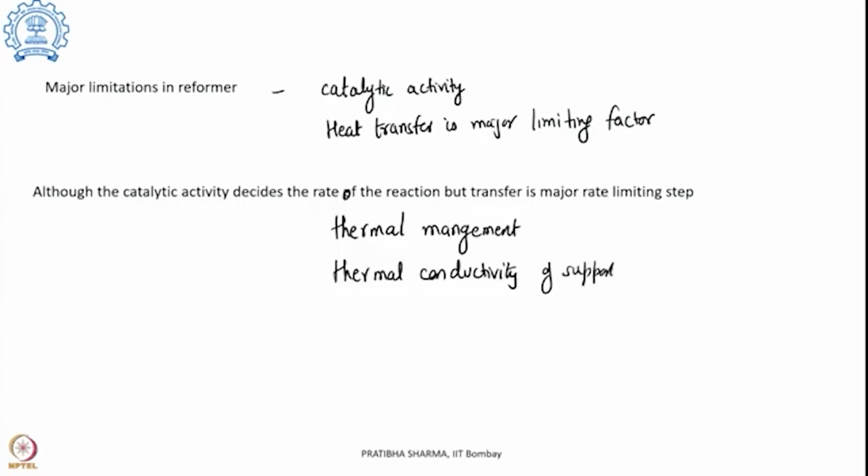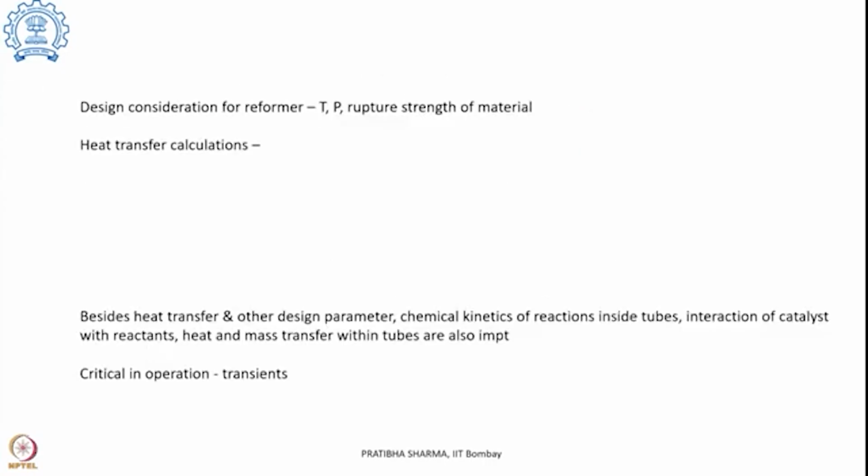There are several heat transfer considerations that need to be taken care of, and these include the temperature, the pressure in the reformer, the material with which the reformer tubes are made, and their rupture strength.